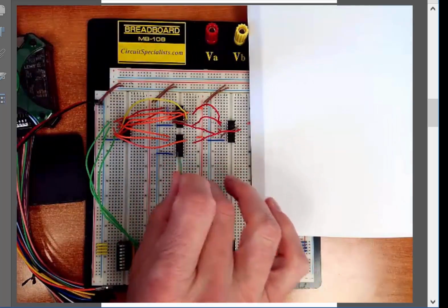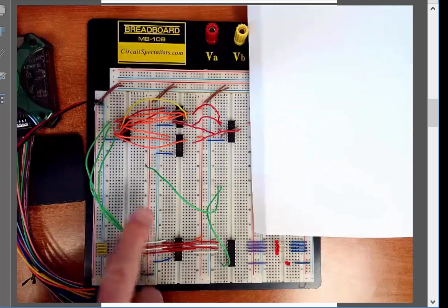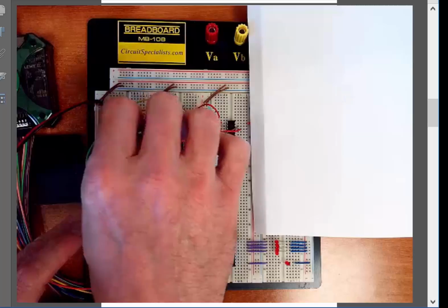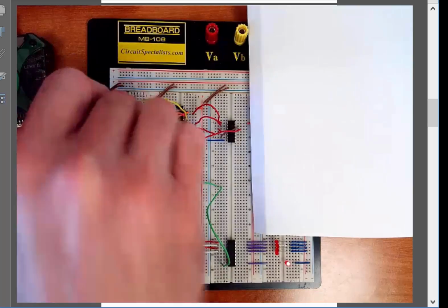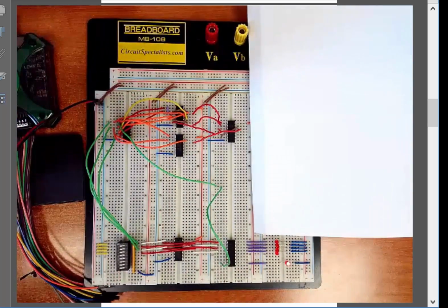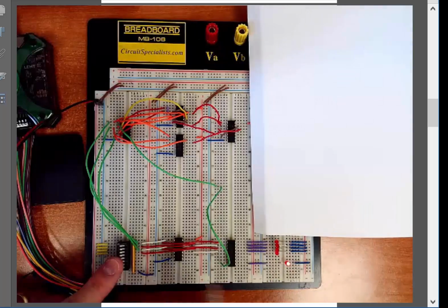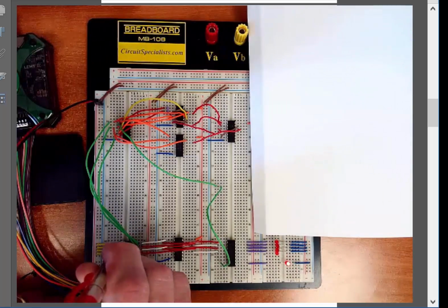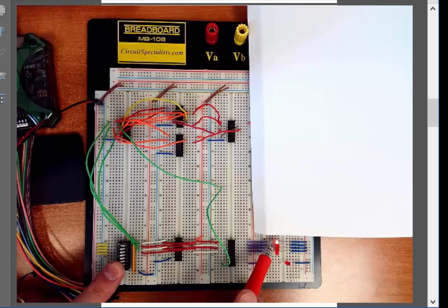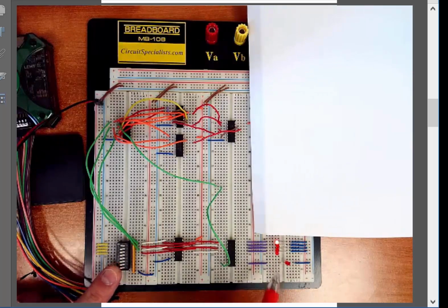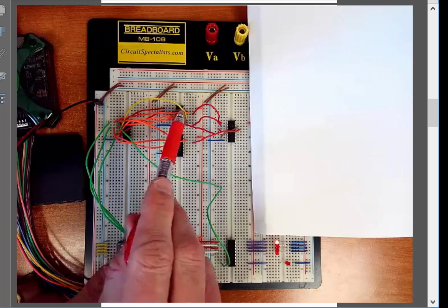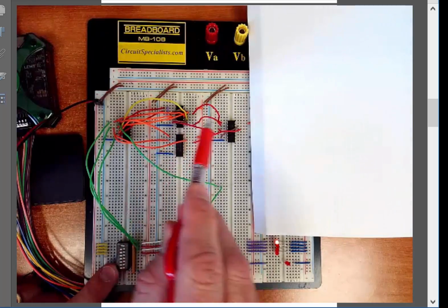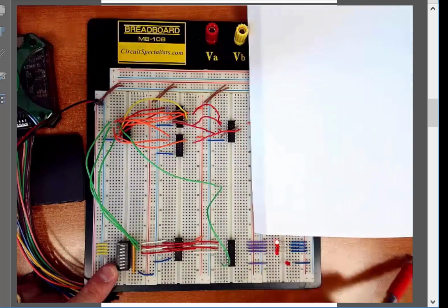But then I can test if something's a logic 1 or a 0 at any given time by wiring into it. If I wanted to test that A was working like the inverter, I could come up here and put it into A naught, and then when A is a 0, look at what happens. It's a 0 there, but it's a 1 there, and if I switch it over, A goes to a 1, and A naught goes to a 0. So I can test that interim calculation. I did that for A naught, B naught, and C naught, and then I built each term for each min-term, and I tested them as I went, and then I brought all 4 of the min-terms over here, and I tested the final output.